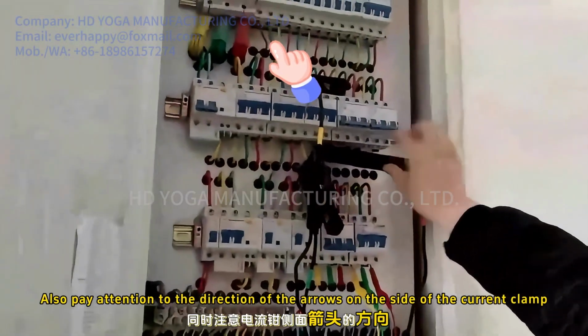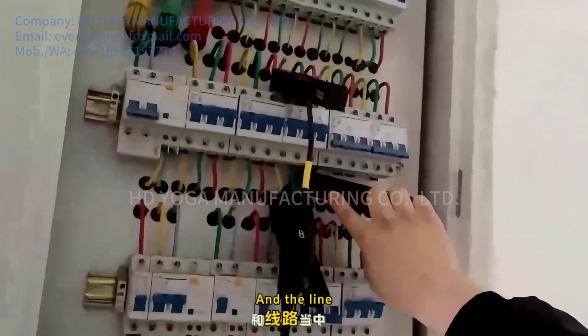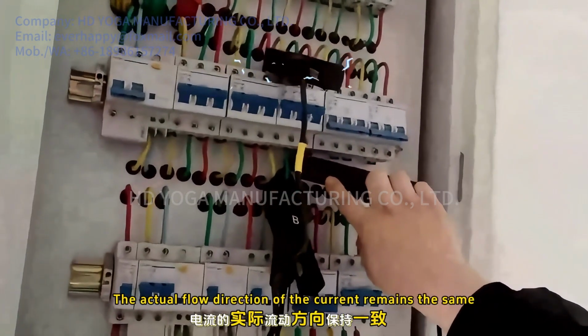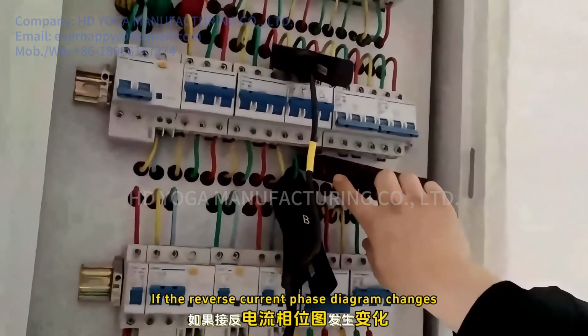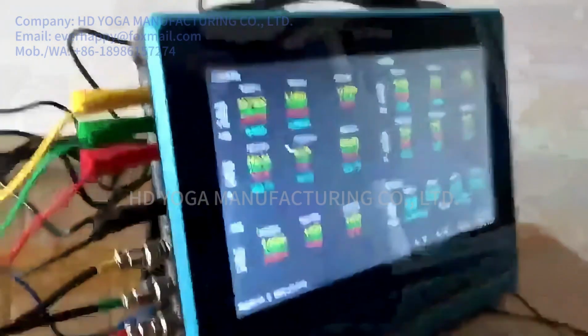Also pay attention to the direction of the arrows on the side of the current clamp and the line. The actual flow direction of the current remains the same, but if reversed, the current phase diagram changes. After connecting the wires, enter the electrical test.